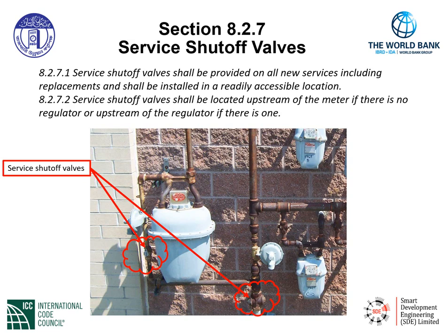The gas emerges from the ground in the lower shutoff valve, as indicated on the rightmost part of the picture, the right bottom part indicated by the arrow. This is where the main gas supply comes up, and from that service shutoff valve, it is piped into a T. The T supplies another regulator, as you can see, on the leftmost side. So, in essence, we could have two service shutoff valves.